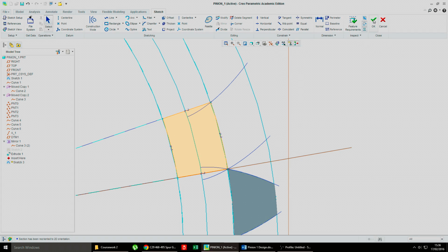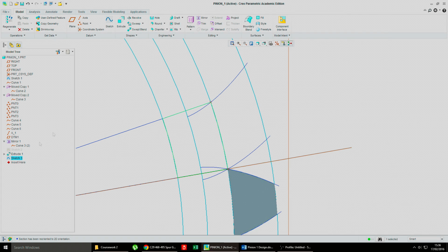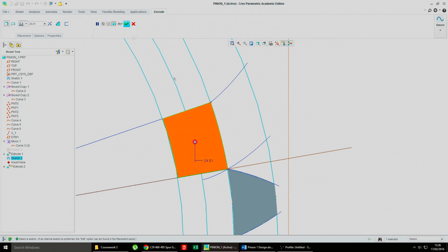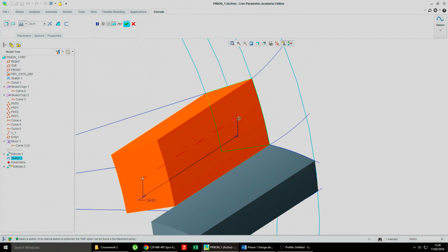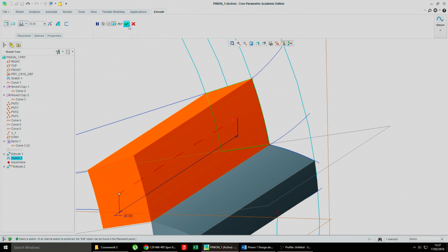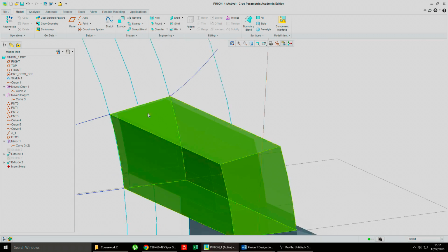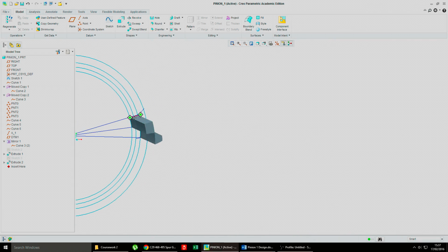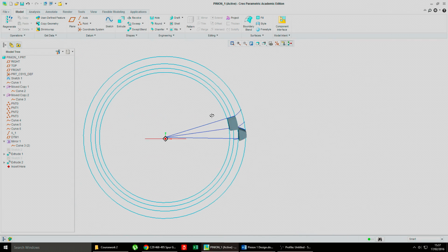So if you click OK, go on to sketch 3, you want to extrude this thing that you've done now. Going to go 30 as well, but the difference with this is it's going to remove material, and I'll get onto that in a bit. So do that. Just click on it normally for now. Now you have these two little things that you don't know what to do with.